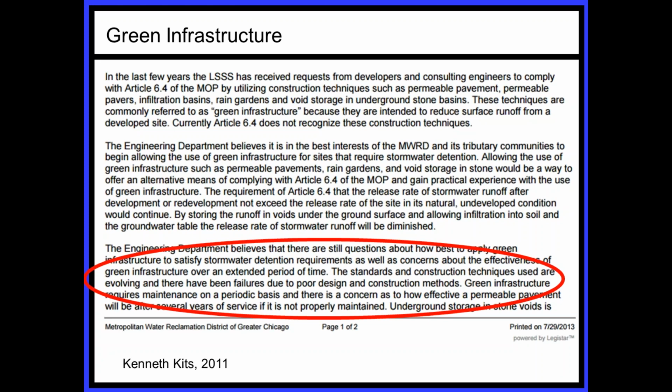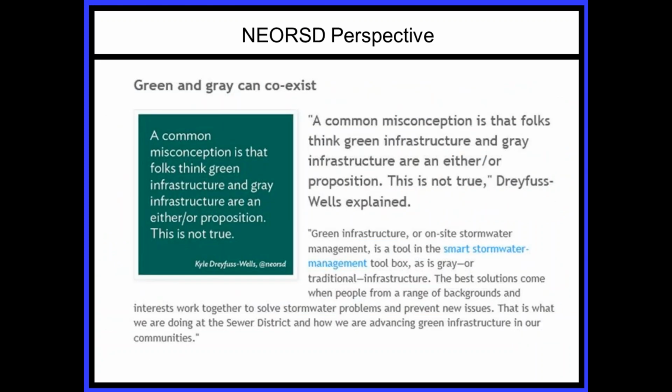But they state that the longevity is still in question because there's not enough history in the Midwest. ADS, as a national company, has seen practices nationwide and is seeing some pullback from traditional green infrastructure because of the lack of maintenance or understanding about the techniques, how they should be used, how we control the volume, and changes in the environmental conditions between the summer and the winter, such as one month it rains 20 inches and the next month it's 5. So dealing with those sorts of things is still being observed.